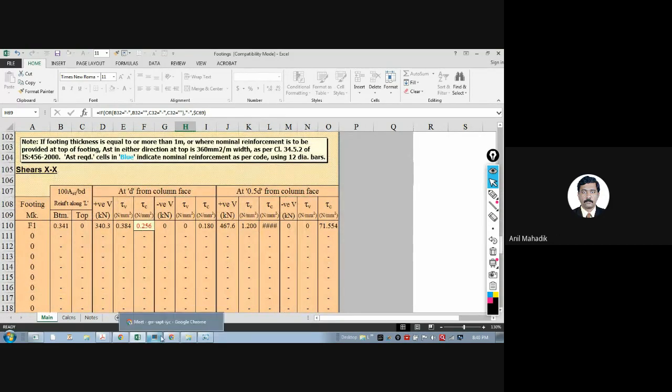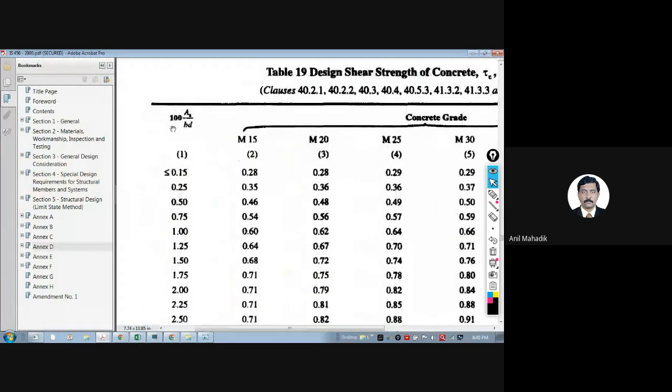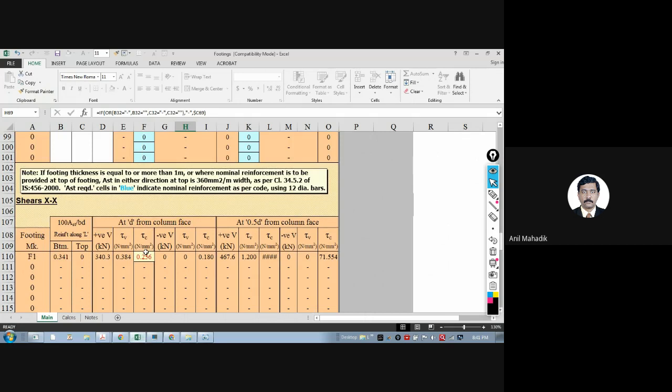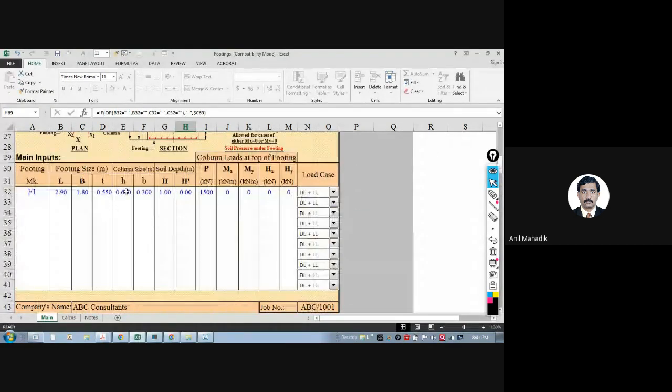Because all of you know that once you change, I'm just telling you what it is depending on PT also, isn't it? So if you increase the PT, see this, as you increase the PT, the permissible shear stress is also increasing. अभी ये 0.25 को 0.36 है and 0.75 को 0.56 है. That means your capacity gets increased, shear capacity, by increasing steel also. But a good choice is increasing the depth so that you can optimize the section. So you should know the dependency of each parameter.